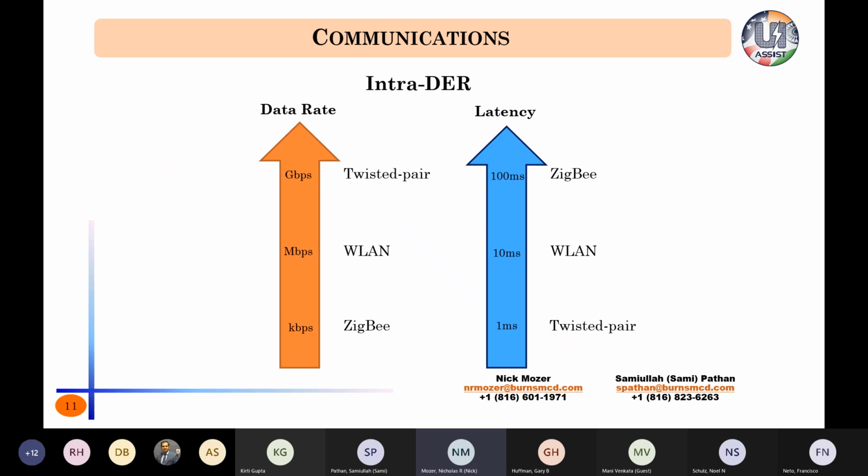And that's really because in alternating current at 60 hertz, one cycle is about 16 to 17 milliseconds. So it's really important to consider how many cycles can pass before your communication needs to reach the other end. Now, if you think about what I said earlier about just getting status points and metering values, then it's not very important because we're talking seconds instead of milliseconds. And Zigbee might be a very applicable option for what you're doing.